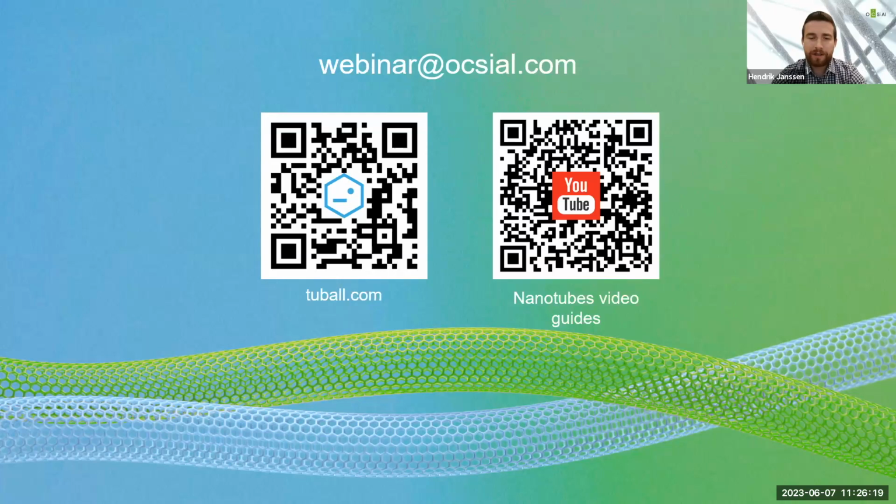One more general question, but I think it's important as well: could you share the resistivity range, antistatic and conductive, and also what's the base color of the nanotubes itself? Okay, we consider antistatic between 10^6 and 10^9 ohm per square, and we consider conductive between 10^4 and 10^6. This is the typical request that we have from our customers. And the base color of our matrix, you will see they are like thick paste and they are black.